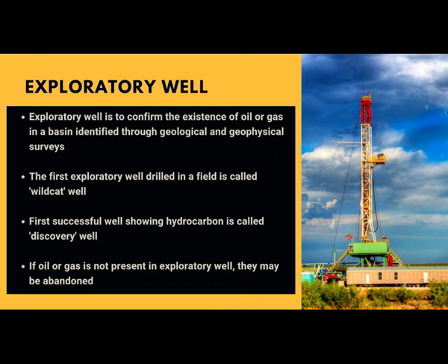After doing the interpretation of the data, now we come to understand whether a particular area has got enough potential for oil. So, once such an idea is formed, then the exploratory wells are dug. An exploratory well is to confirm the existence of oil or gas in a basin identified through geological and geophysical surveys.